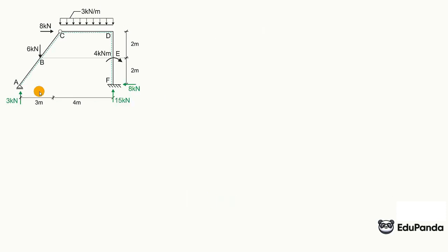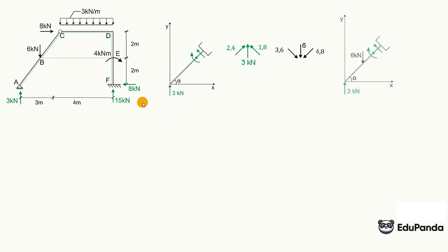So here we already have drawn, instead of reactions I have written their values, that 8. That horizontal reaction was to the right, but a minus came out, so I drew it to the left with a plus. Bottoms are marked, so we know everything. These are our decomposed forces. This is our cut and this cut here, which will be between point A and point B, meaning we only see these 3 kN, and when we move further with the cut, we will already see the 6.